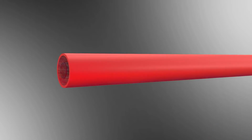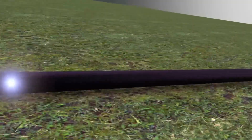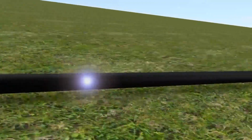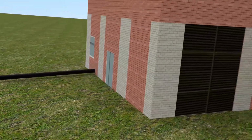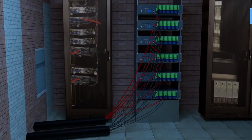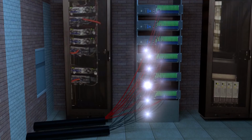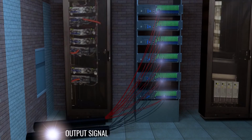The optical fiber we have just constructed won't be able to carry signals for more than 100 kilometers. This is due to various losses that happen in the cable. This loss of signal strength is generally called attenuation. Absorption and scattering are the main reasons for signal attenuation. This is why you see amplifiers in cables after a certain distance. They boost the signal strength and allow signals to be transmitted over a long distance. The power required for the amplifier is drawn from nearby sources.